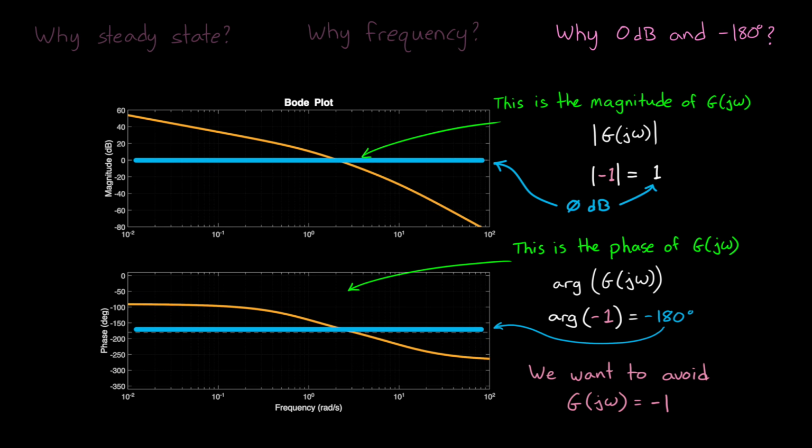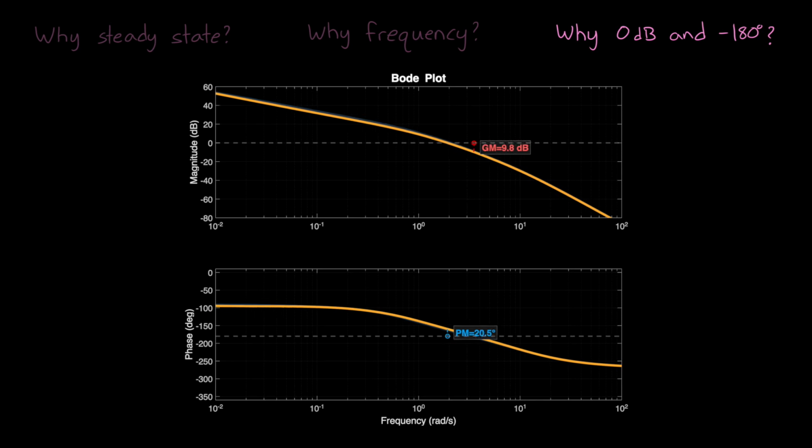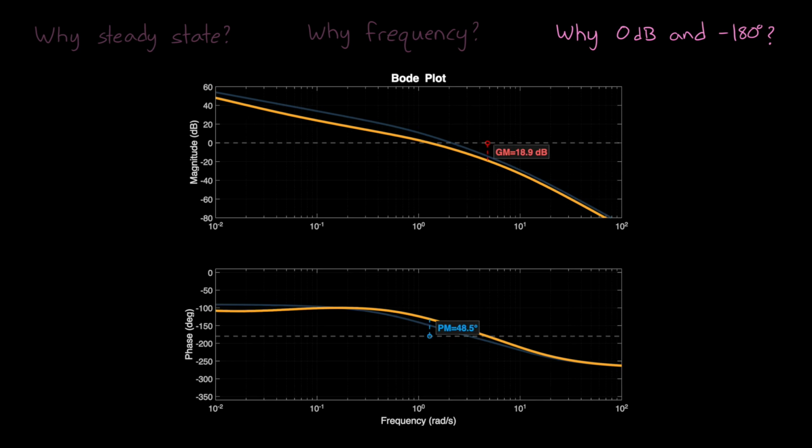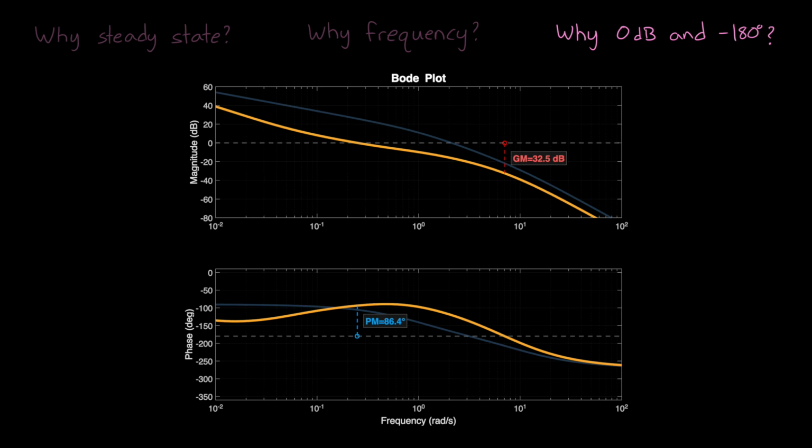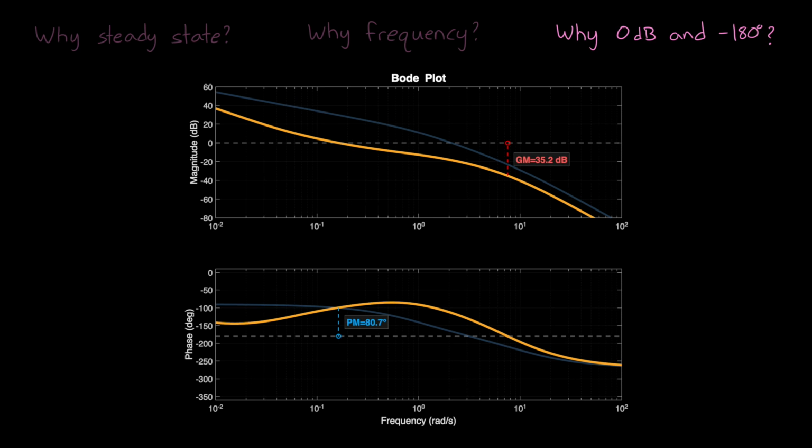And that's what makes the Bode plot a powerful tool for designing closed-loop control systems, because now, when you add poles and zeros and gain in the form of a controller, you have something concrete to design to. When you're shaping the frequency response using a Bode plot, gain and phase margin become the targets for robustness in your design.